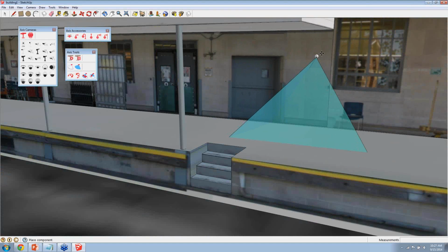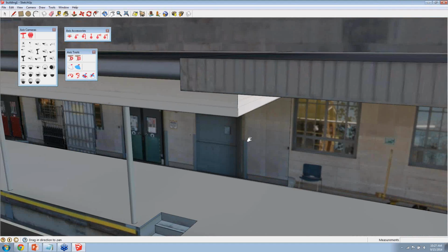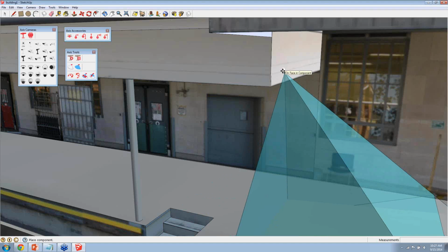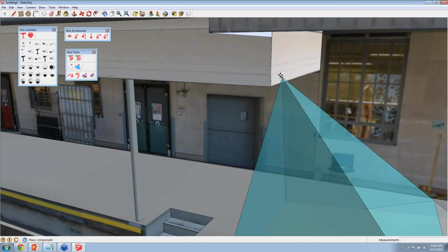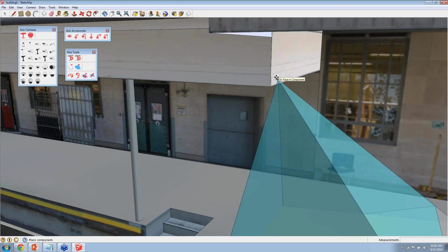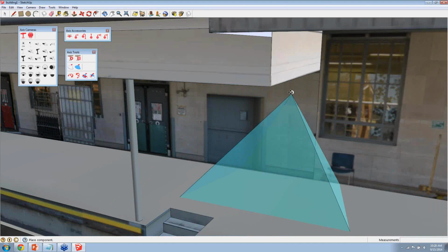So as far as snapping to this wall, it assumes I'm wanting to mount this camera on this wall. For example, if I move that up though, the snap location of the camera moves up as well. So you can see it's flush against the wall here, but if I move it to this overhang, it automatically snaps orientation to a different face. Pretty useful.